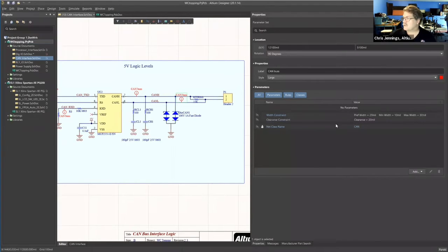And in this case, you can not only create net class for routing rules, but you can also add the rules here. Now, in this particular case, this is a useful case for the CAN bus because you need particular connections. But some of our customers that I've physically been on site at have very high voltage nets, like solar panel, power supplies, rectifier, inverter type schematics. They very clearly need to label all the high voltage lines or all the high current lines so that they can point that out to the layout engineers.